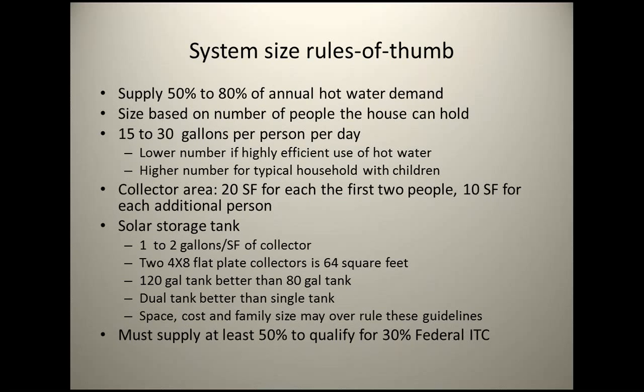So that's a consideration. The gallons for the size of the collector is important, because if you don't have enough storage for the collectors, what happens? You get a lot of energy, and the tanks get really hot, and then you drain the tank really quickly because people use the water, and then you're back on using the conventional source again. So the larger the tank size, the better that whole thing is. But there are limitations on the weight of the tank and how much space you've got.